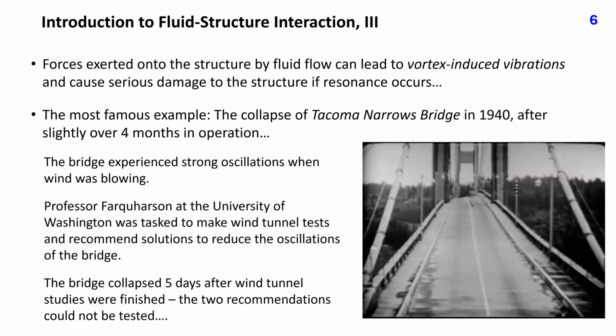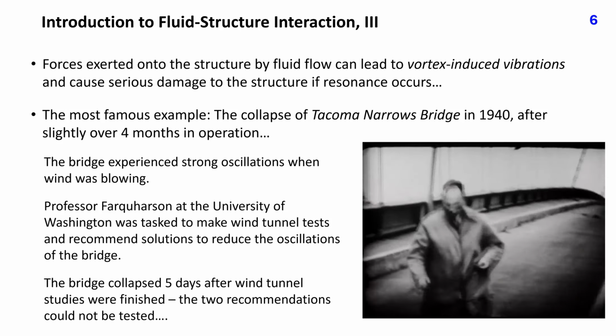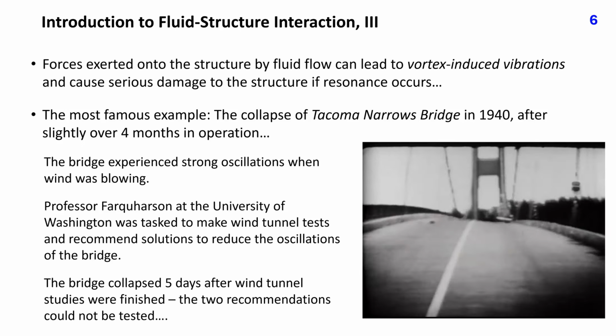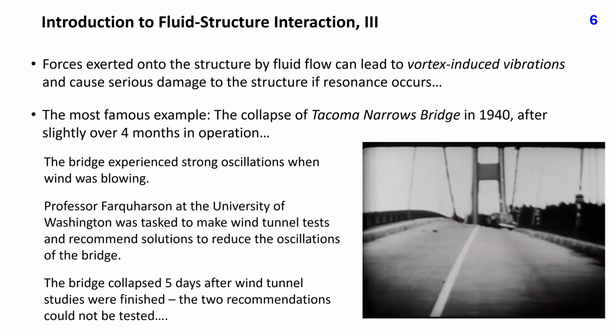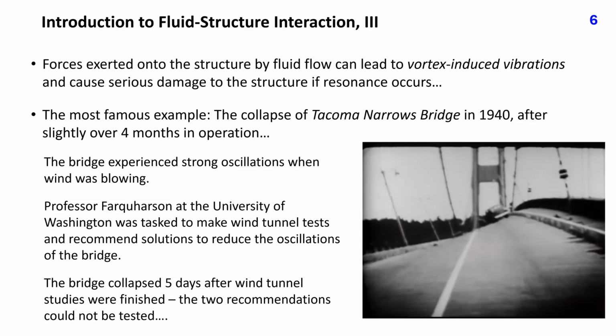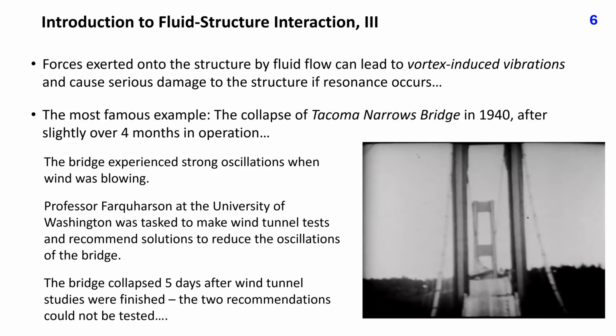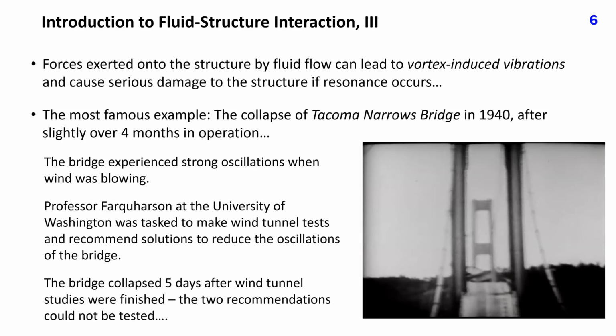Forces exerted onto the structure by fluid flow can lead to vortex-induced vibrations and cause serious damage to the structure if resonance occurs. The most famous example is the collapse of Tacoma Narrows Bridge in 1940 after only slightly over 4 months in operation. The bridge experienced strong oscillations in use when the wind was blowing.